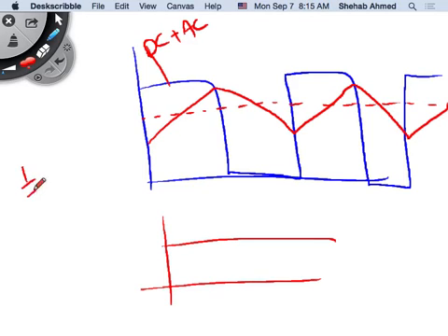That's the 1 over the period integration of V of t over the period. That's this value here, for example. So that's the average value. And then there's a lot of AC component. The amount of AC component that you see at the output will depend on the filter design. So here I've removed some of the AC component.